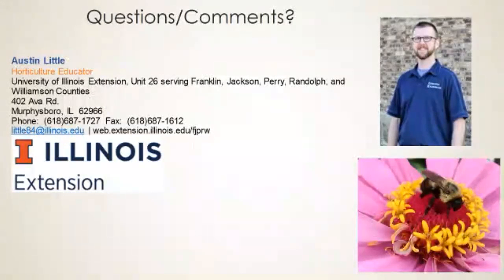And so another problem with the native plants is that a lot of them need a deeper substrate because they have really naturally deep root structures. And they like to kind of burrow deep into the soil. So that's not really compatible for a shallow green roof.